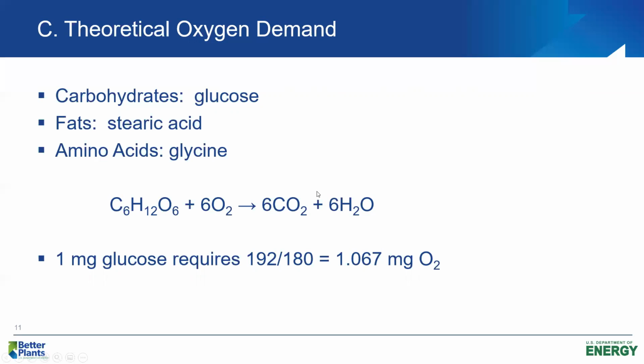because that's what this equation here shows, the oxidation of glucose to CO2 and water, and the theoretical oxygen demand of glucose. 6 moles of oxygen has a molecular weight of 192. 1 mole of glucose has a molecular weight of 180. So the theoretical oxygen demand of glucose is about 1.07 milligrams of oxygen per milligram of glucose. So that's an estimate, again, of the ultimate oxygen demand of glucose.